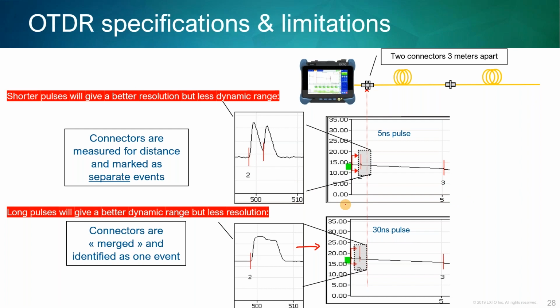Multiple pulse widths, more than just 2, because I need a short shot to look at my office information. I need an intermediate pulse width to look somewhere in the middle, and I need to scale that as the fiber gets longer and longer. And so you have to determine what you're going to do. So a lot of folks that are running OTDRs are doing a short shot to look at the office information, then doing a long shot to look at the span. It's not uncommon, particularly on backbone systems.